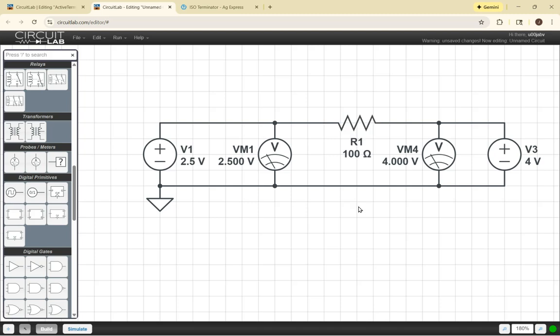If I were to remove this resistor, if we just took it out of the circuit, nothing really changes. However, the thing that I can't do is remove this resistor and replace it with a short. I cannot have 2 different values of voltage in parallel with each other, because the rules of parallel circuits say they have to be the same voltage. Therefore, they must become the same voltage, or we must burn the wires up that are connecting the 2 voltage sources, which is typically going to be the case. So if you try to take a 12-volt battery and put it in parallel with a 6-volt battery, you know just what I'm talking about.